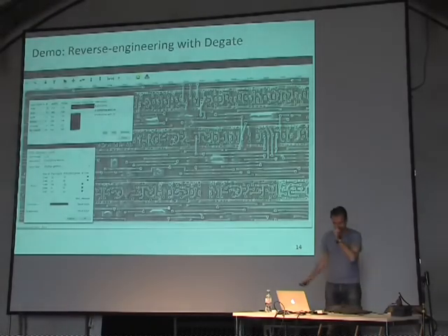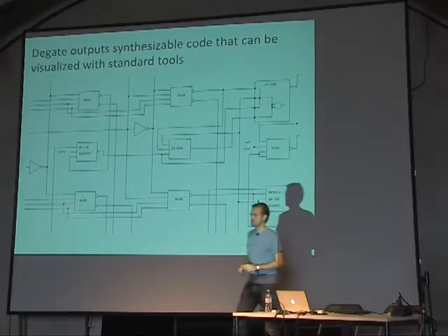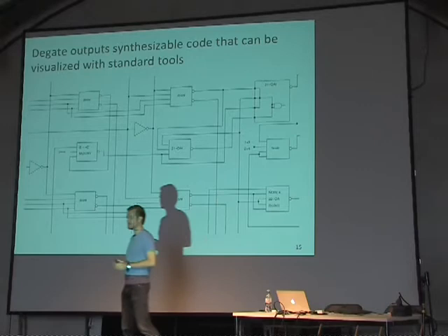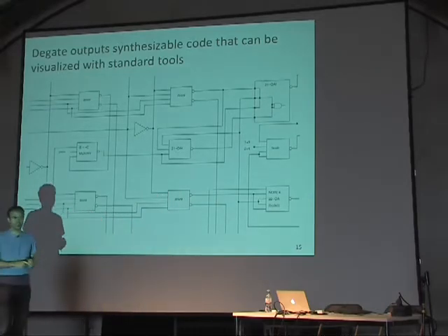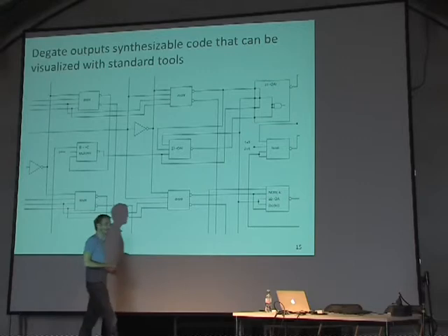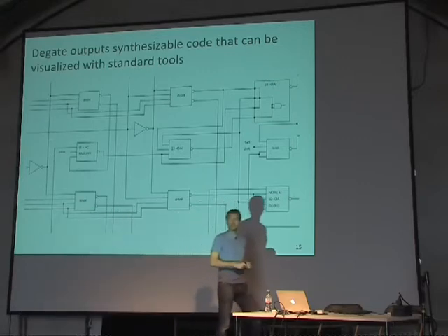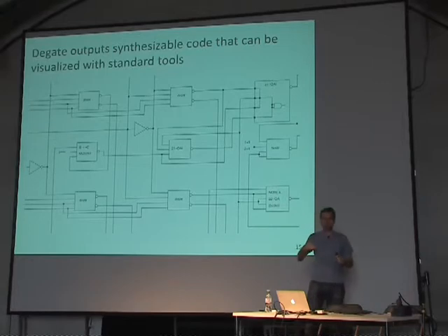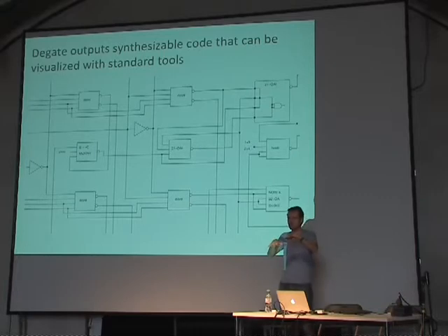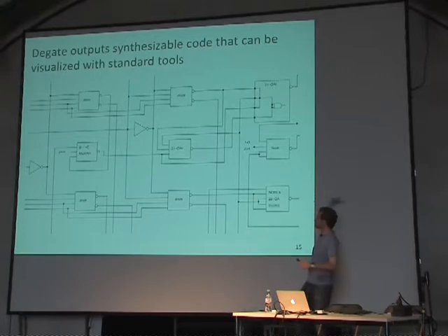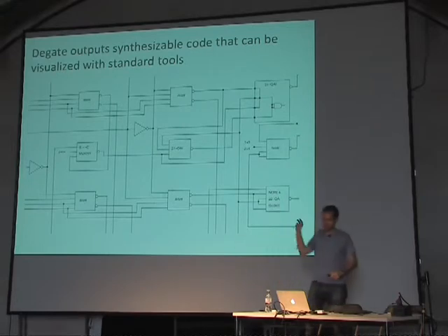All right, so that's the type of output to be expected by this tool. It does export Verilog and VHDL, but of course there are viewer programs for that. It's not quite assembly or binary, mostly because it's highly parallel. Instead of one instruction after the other, there are maybe 100 streams, 100 threads executing at the same time. At the end of the clock cycle, they all computed something at different speeds. This is the data flowing through from left to right. Each of these functional units performs some operation on the data, some mathematical function.